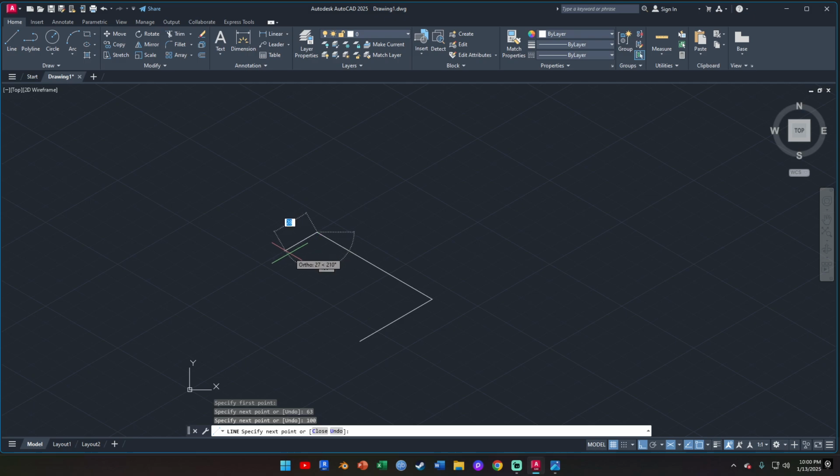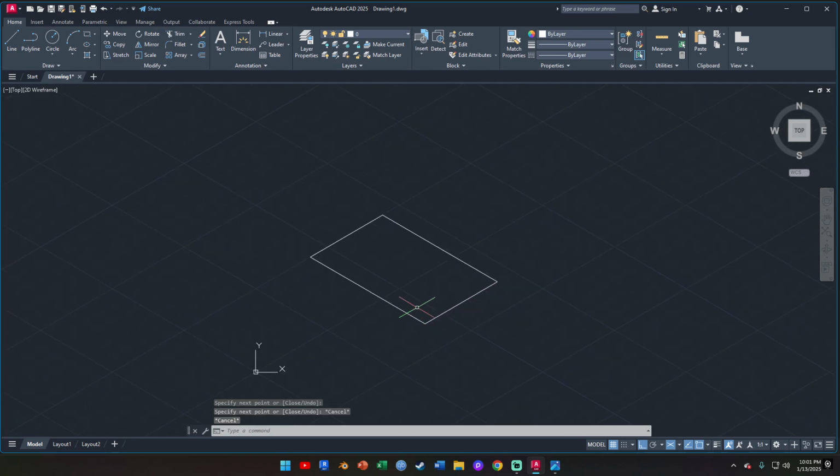So you move back here now on the right receding axis. We know that is 63, so you type in 63, enter, and then you close off the base by drawing the final line here. And remember, if you want to stop drawing a line, you need to press the escape key. So we have the base of the box here, which is 63 by 100.